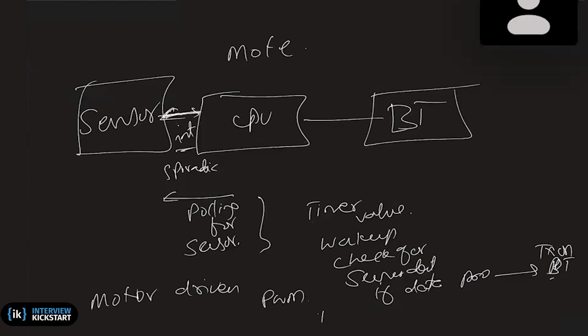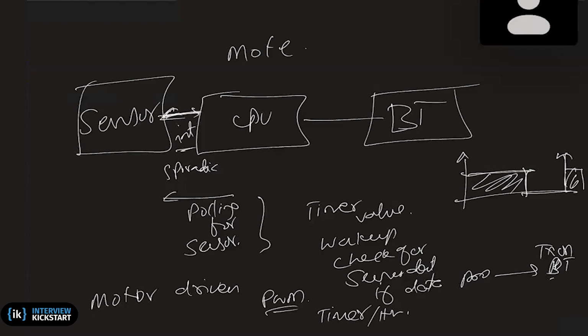These signals are generated from a hardware timer, based on whatever the pulse width is. So you would have a pulse interval and an active interval: the GPIO line is on for this long and then off for this long. So you are using a timer in any PWM situation, but not as a generic timer, rather for a special purpose. These are all periodic events, but that has nothing to do with the timer tick. If you're doing it in software, like polling through a timeout value, then the timer ticks come into the picture. Oh, I see. So here the interrupt is the event we're talking about.